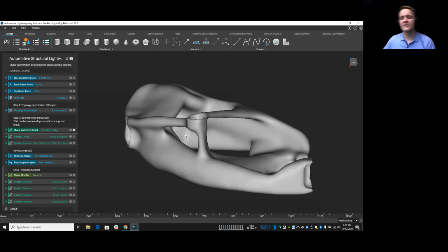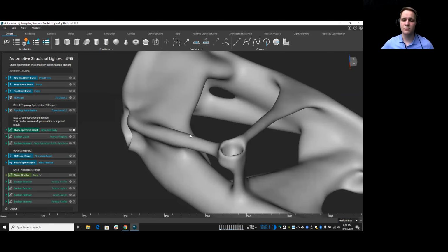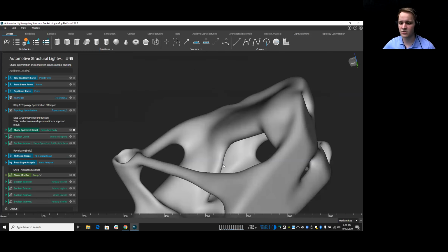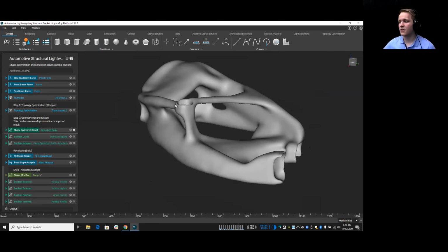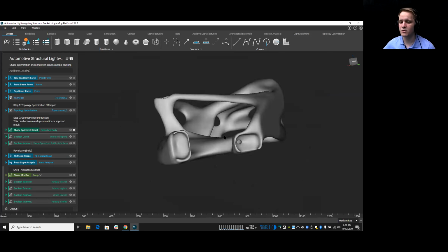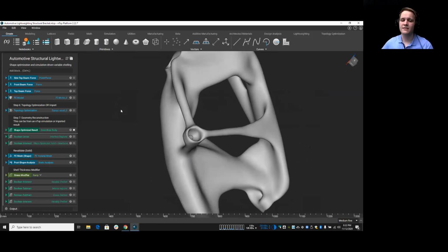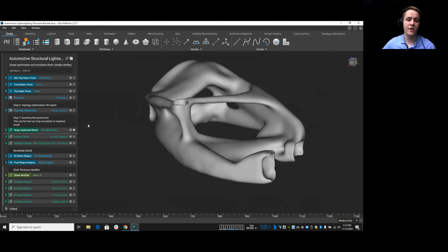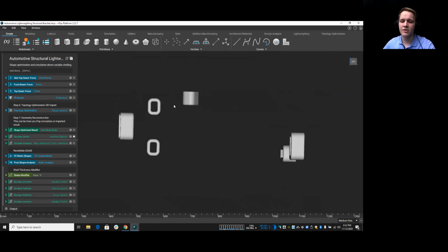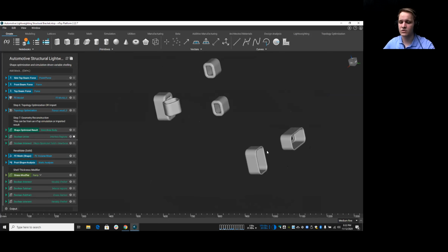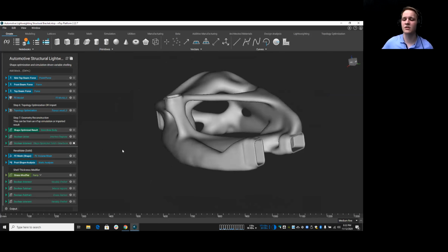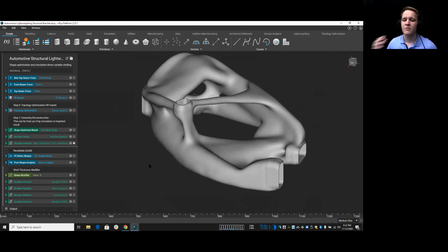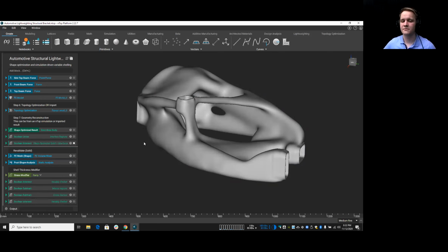So now that I've solved that problem, I have a smooth, usable geometry, no stress concentrations, no thin regions, all that sort of stuff. But we might notice that I smoothed away my connection regions. So that's a new problem that we've created here. But with implicit modeling, I grab those volumes out in 3D space here, those ones where I need the sharp corners and the sharp features, and I just do a basic Boolean operation back to my geometry. So now I have my nice sharp features with a smooth transition into my optimized geometry here.